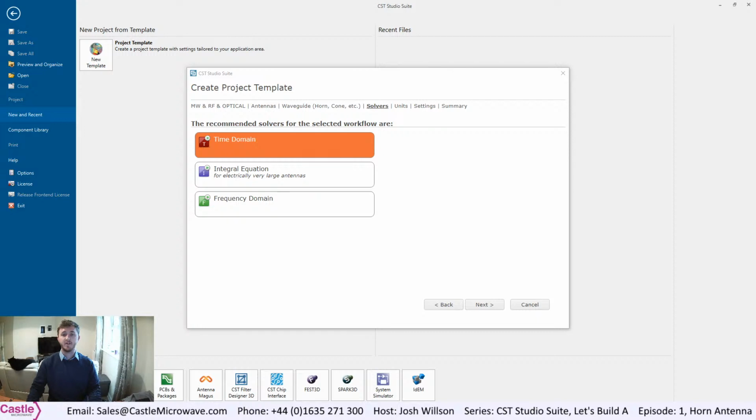However, the transient solver applies some highly advanced numerical techniques like the Perfect Boundary Approximation in combination with the thin sheet technique to allow accurate modelling of small and curved structures without the need for an extreme refinement of the mesh at these locations. This allows for a very memory efficient computation together with robust hexahedral meshing to successfully simulate extremely complex structures.